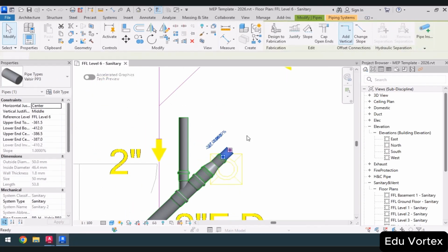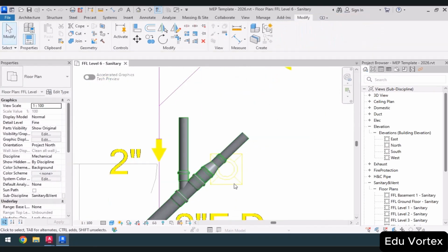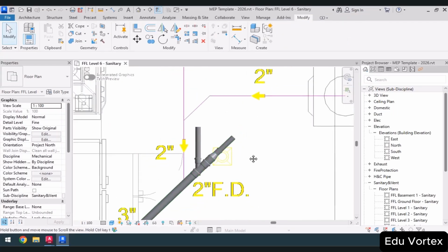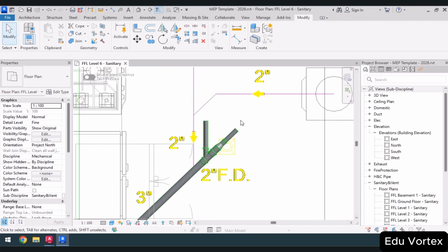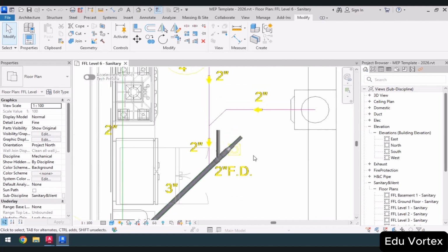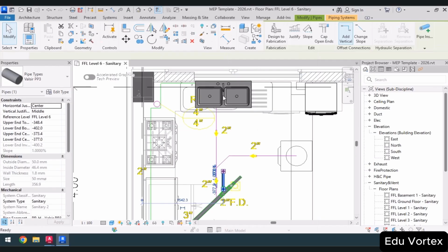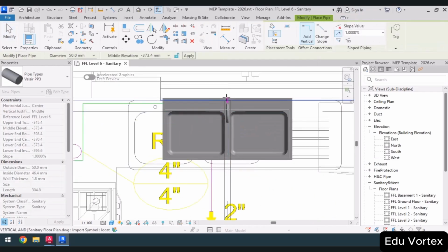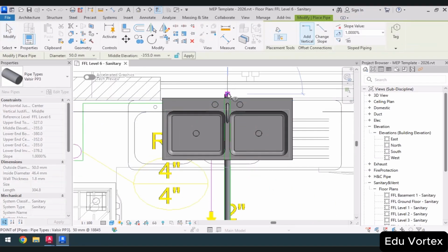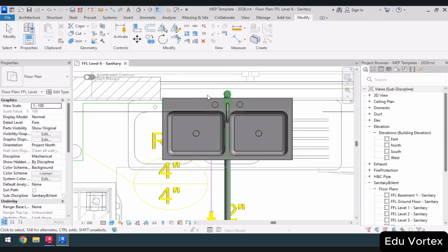So now I will right click and use the draw pipe command to bring it slightly forward. According to the map, I cannot place the floor plane drain exactly where it is. It needs to be moved slightly forward due to the conversion. Therefore, I need to guide a trap for it. I can leave a comment indicating that the position of the floor drain can be slightly adjusted. So I will continue until I reach the wall and go up to the height of 500 millimeters, applying each step as I go. I will change that 90-degree elbow now.